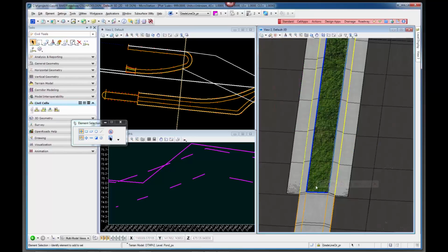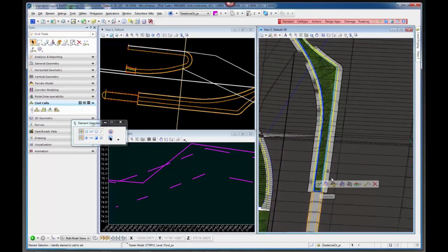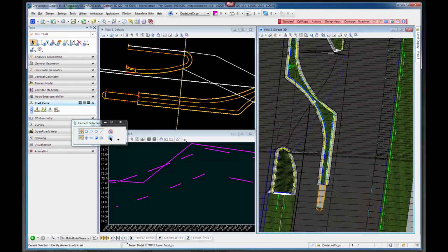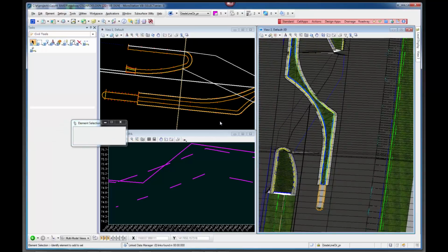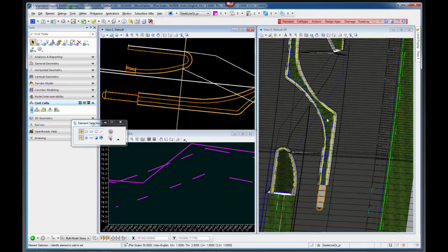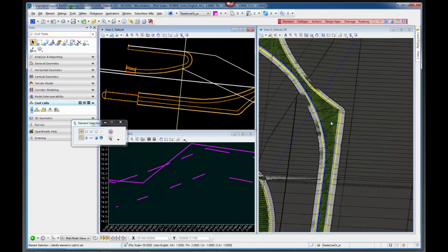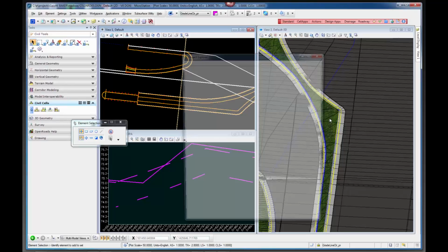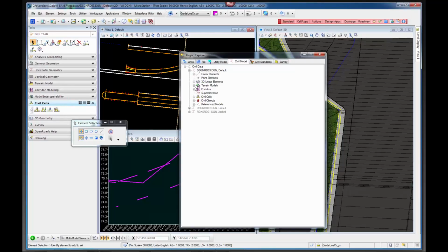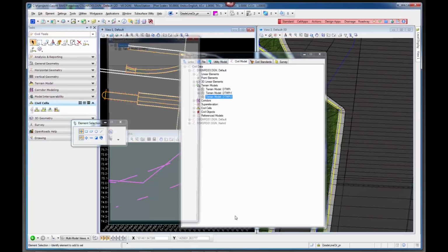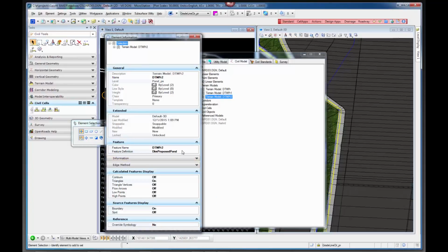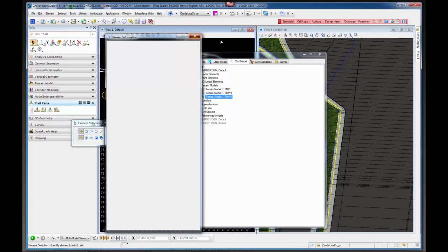And then you'll just use those two lines to create the terrain, and then use, in this case I used the pond terrain and then I modified the element template for the pond terrain. So how do you do that? Well, like I said, if I were to go to my Project Explorer, I'll see that I have in here a terrain. If I go to the properties, it's using this proposed pond, and that happens to be this grass median across the top.